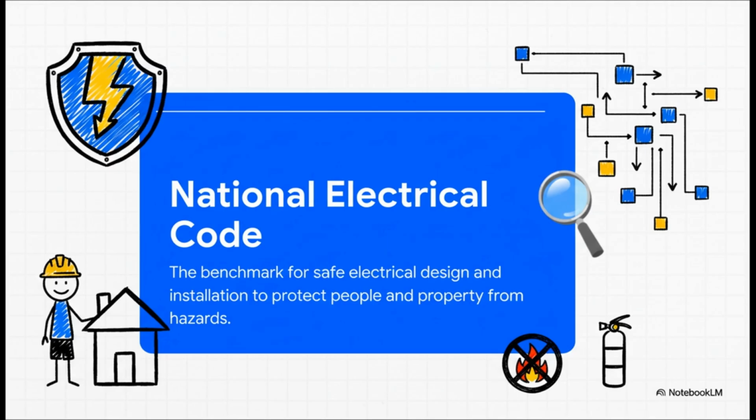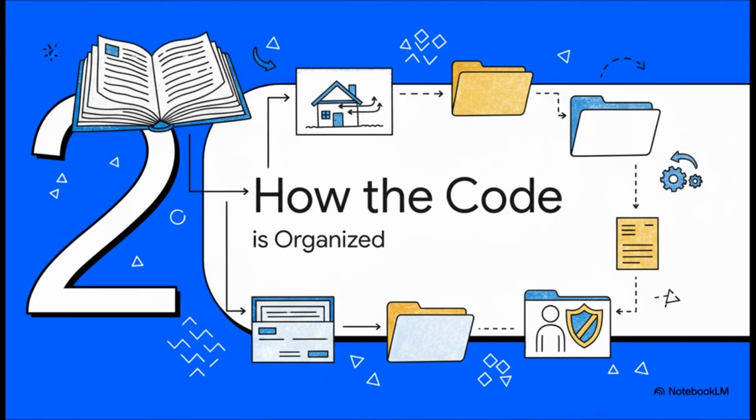Perfect analogy. Okay, so if those are the pathways, what about the system's defense? How does it protect itself? That's the crucial protection piece. And Chapter 2 handles the 2 most important defense mechanisms. First, we have overcurrent protection. Article 240. Article 240, this is the system's main defense. It's your fuse or your breaker, and it makes sure that when a fault happens, the power just stops before the heat can cause a fire. It's the ultimate safety brake.